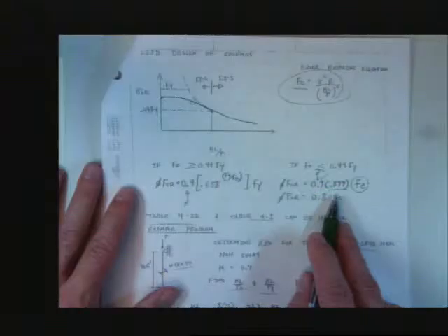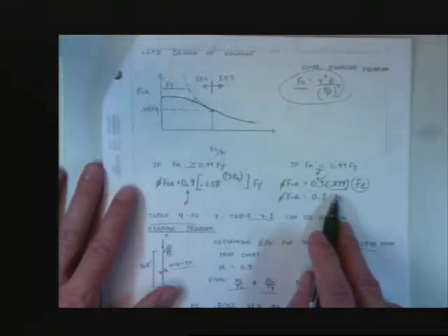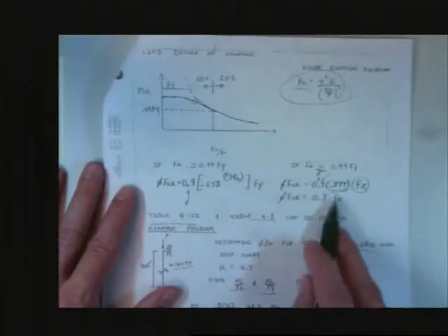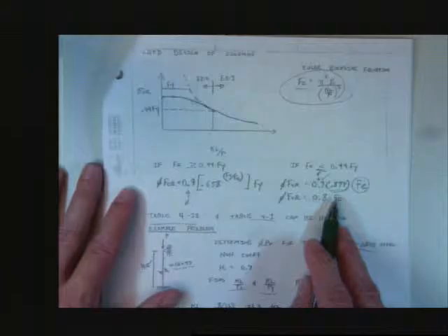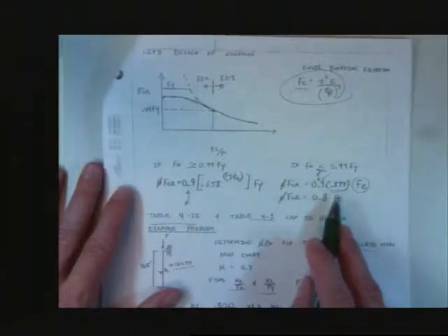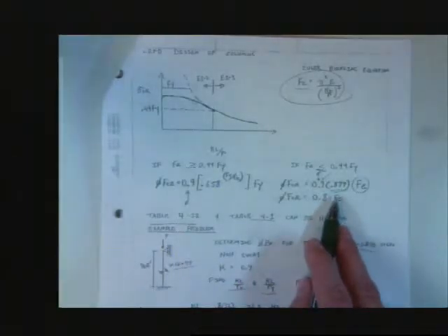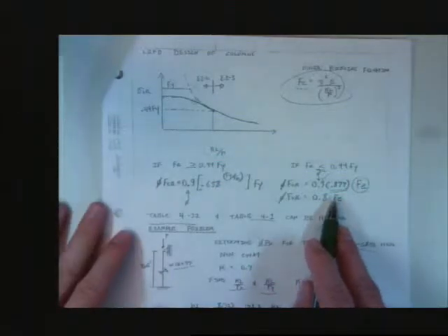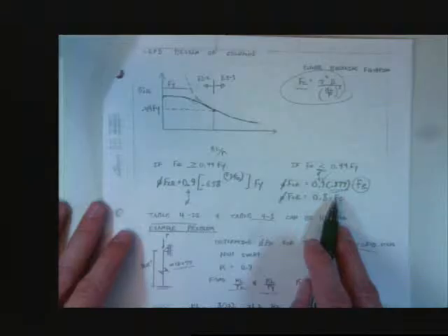If you suspect that your column's been beat up, been hit with some stuff and you hammered it back in place, or wasn't built per AISC specifications, you might want to consider using a lower reduction factor than 0.877. There's sadly no guidance at all on that, but it is what it is.